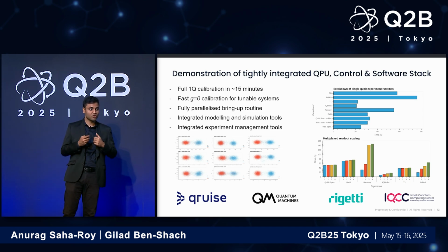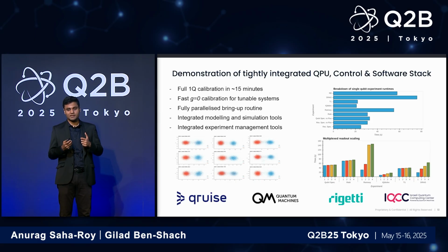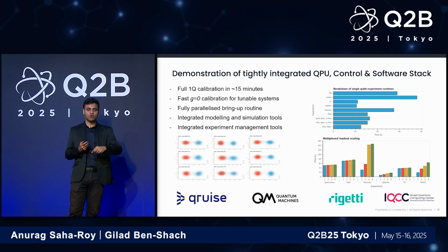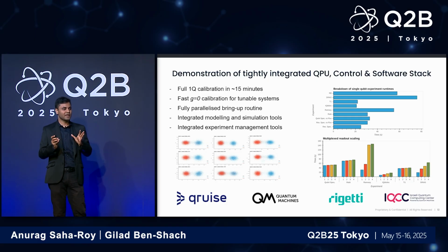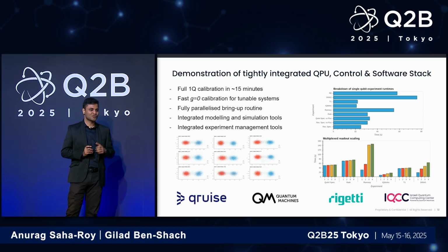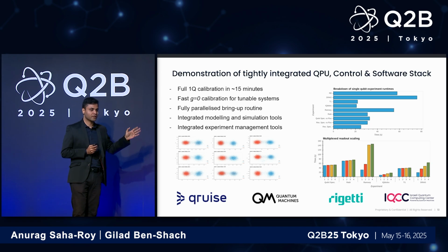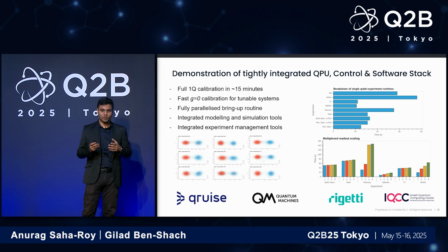So this is a tunable qubit tunable coupler device, essentially, which means that even though you only have 9 qubits, all the couplers are also transmon devices, and you can tune all of these devices, which means you really have a lot of knobs that you need to correctly park in the right places to get very good single qubit and 2 qubit performance. We were able to do that in under 15 minutes and also efficiently park all of the qubits in a place where they are experiencing the least amount of crosstalk. And this is all parallelized. We again use the fantastic firmware that Quantum Machines provides with their control stack to easily run these experiments at the same time on all of the qubits.